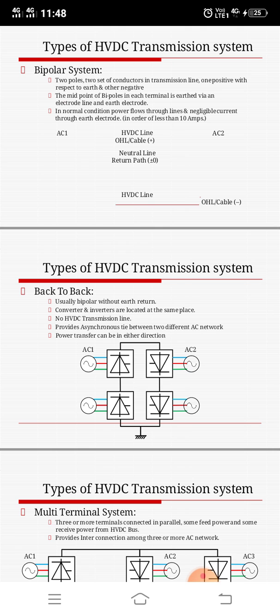The conversion from AC to DC at the rectifier station and from DC to AC at the inverter station are performed. A point-to-point transmission requires two converter stations. The roles of rectifier and inverter station can be reversed, resulting in power reversal by suitable converter control. In the very beginning, we join the HVDC transmission from the rectifier station to the inverter station at the end. This is the most important point.